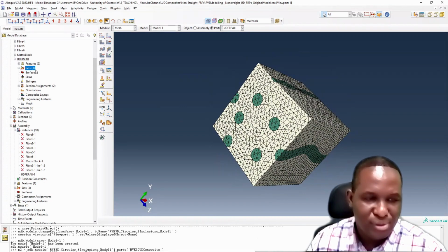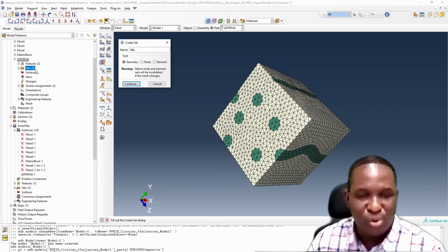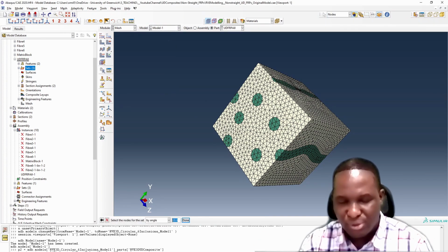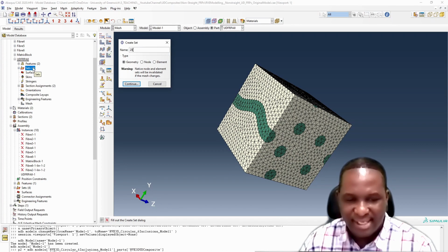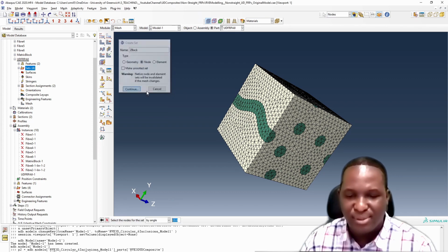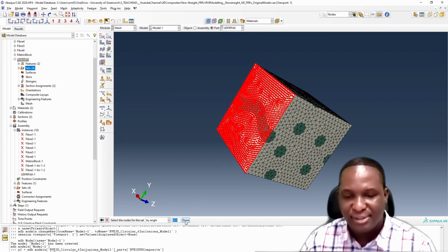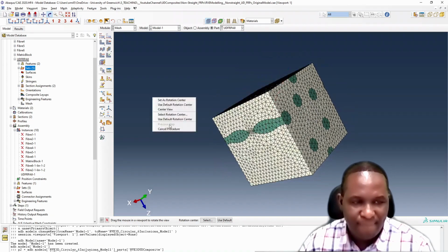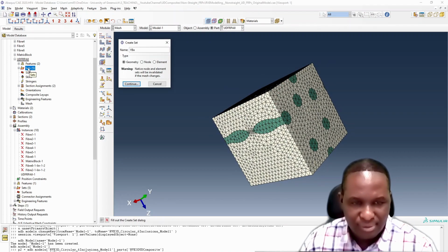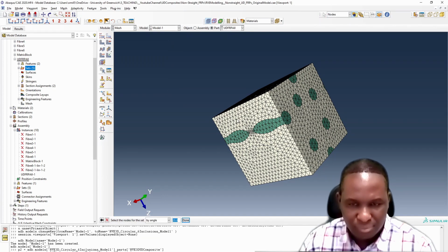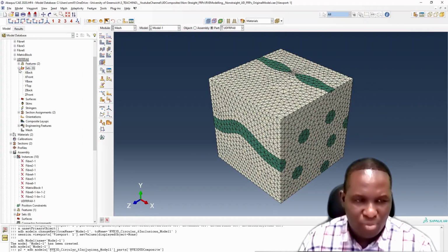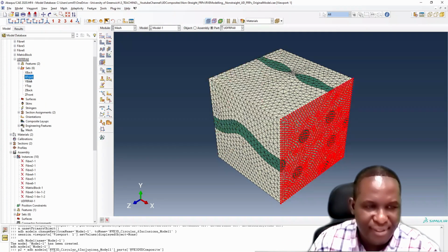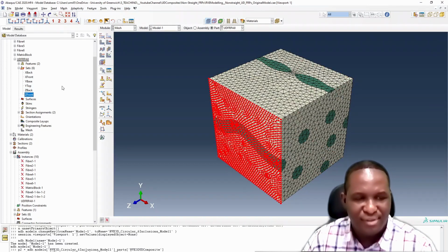And like we always do, the first thing we're going to do with this boundary condition is create nodal sets for all the faces that we're going to use. So X face, X front. I like to use a node option so that makes it easier for selecting the point. And we want to change this by angle. So we hover around the front edge. Okay, so that's the node for X front. So Y top. So that's for the top. So we're going to do the same for all that. Okay, so we've created all the sets for all the faces, and we can cycle through to make sure that we have it correct. So this is fine.